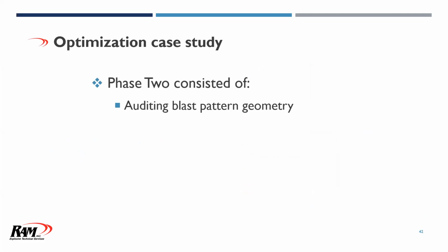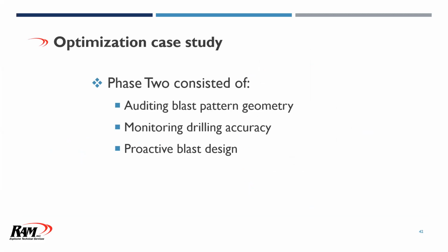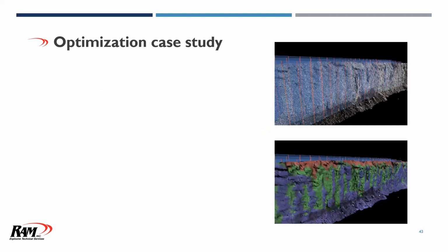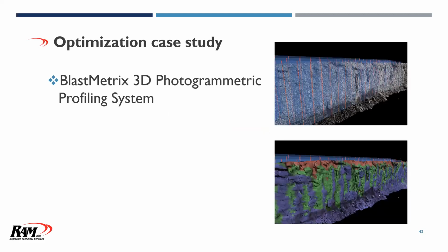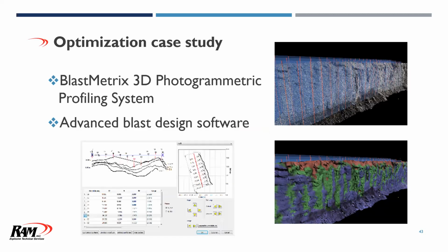One was first auditing the blast pattern geometry, monitoring the drill accuracy. And again, the drill log is a very, very critical part of this. And moving forward with a proactive blast design. In order to do so, they used the Blastmetrics 3D photogrammetric profiling system and the advanced blast software to be able to capture and get those minimum burden designs.